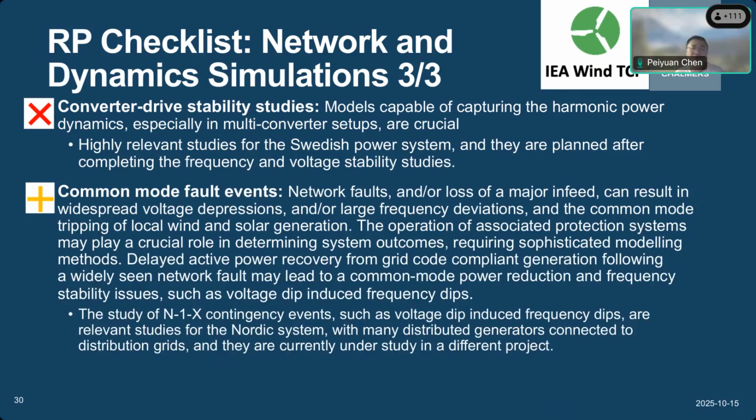Yes, converter-driven stability has really become a center of discussion in the Nordic system, and there have also been grid code requirements coming out on how, for example, wind parks should test so that they fulfill the stability requirements in the frequency domain. So that will definitely be a follow-up study after we have checked the previous red crosses.